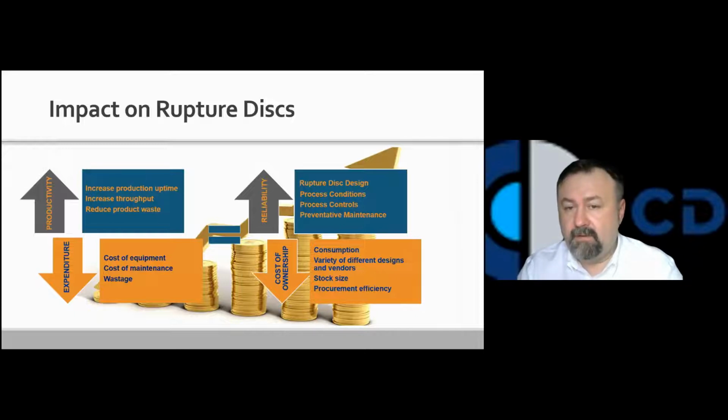And naturally, the frequency of preventative maintenance, because at this point in time we cannot positively or with any assurance say how long the rupture disc can survive in process. What we can do, and we're going to talk about this later on in the presentation, is mitigate certain process conditions to increase the longevity and reliability of the rupture disc and have a positive effect on the process.